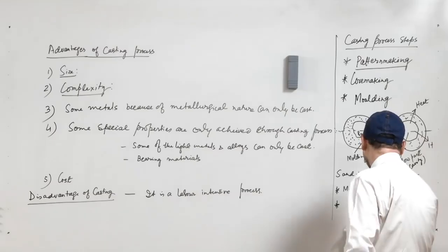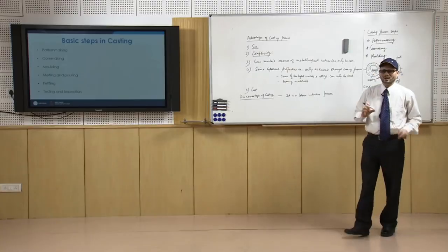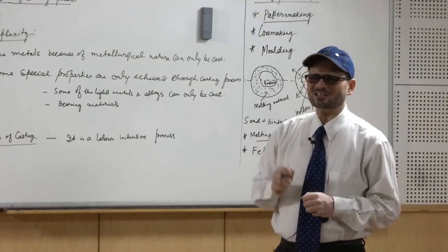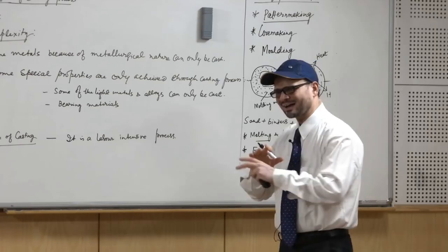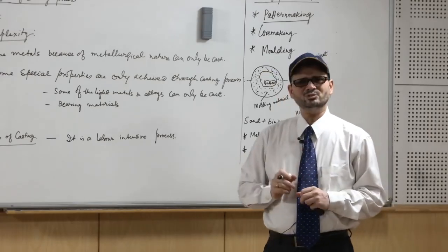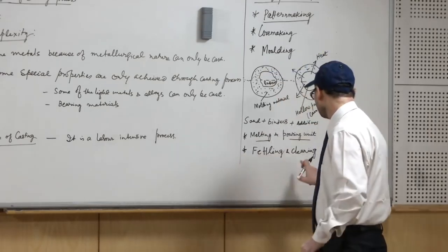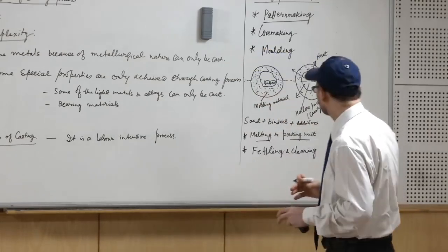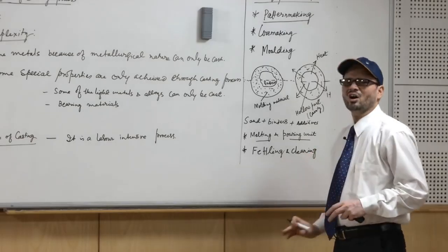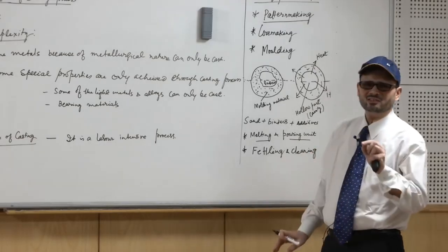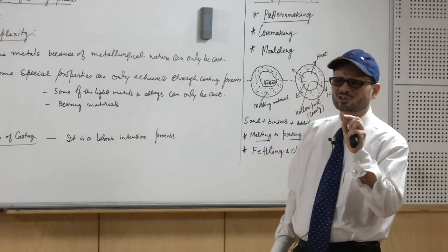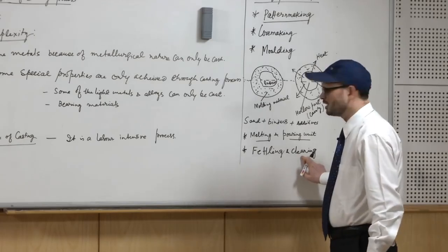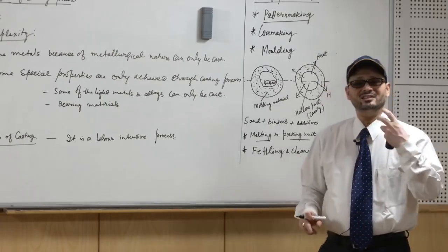So, in this case you have the provisions for either breaking the extra attachment, or you may go for cutting these attachments by flames or by electric torches. For cleaning you may use the liquid solvent based agents, or you may use solid particles of iron shots, they also are used. So, that is by shot blasting. You may use sand also, like sand blasting.